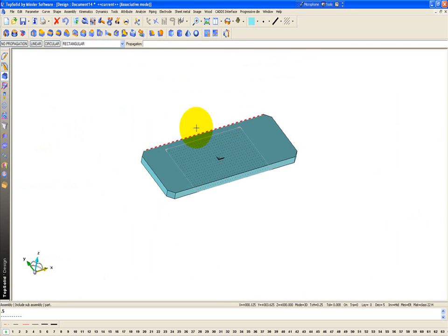I'm going to go ahead and fill the screen now. Say no propagation, other component, and I'm just going to pick them from my list here. I'm going to say staging block 1. I'm just going to drop it in here. I'm going to say take that bottom face to this face. Say OK. I'm going to take this face to that face. I'm going to say OK.